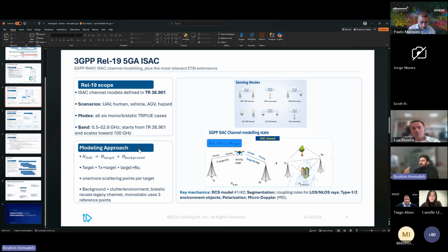I wouldn't call them downlink because in this case there's no downlink. It's just transmission and listening. For example, if you transmit CSI, DMRS, PRS, or SSBs, you wait for some time, the listening time, and then based on some prior knowledge about the environment, you can detect, as done by the demo. You always have the reference measurement, the idle state, and whenever there's a change, you detect those changes.